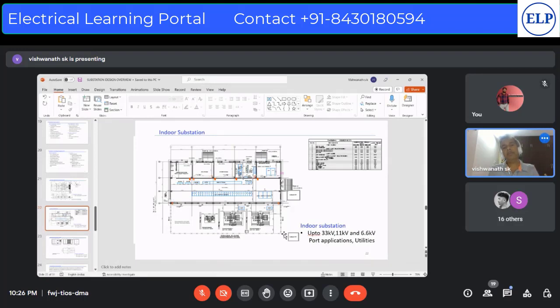How the medium voltage switchgear panel dimensioning will be done. What the transformer dimensioning will be. What all the database you need to create. And if you're using the battery charger with planted type batteries, what separate room should be provided? What are automation rooms? And all these things we talk about in your equipment layout.